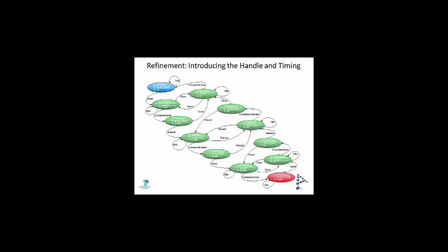In further refinements, what you need then to do is these idle loops, which at the moment is the notion of a cycle, they need counts on them. Because if you go to the Airbus specification, it'll tell you precisely how much time it requires to do that before it's completed. And so now what we do is we add the timing constraints, and what we can show through refinement proof is that it still obeys the original properties of the system, that you can never have the gear moving when the door's opening or closing.